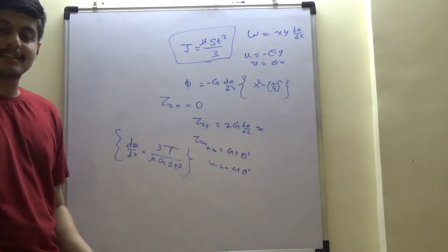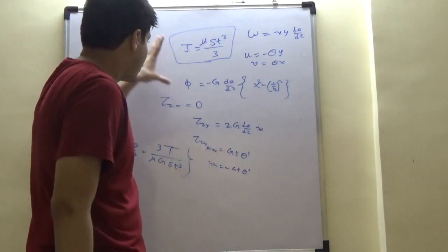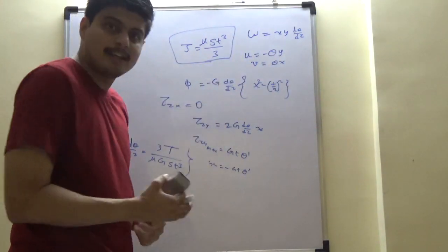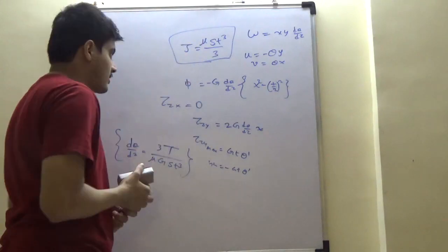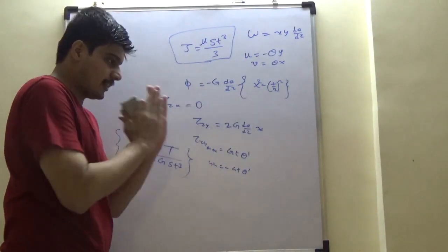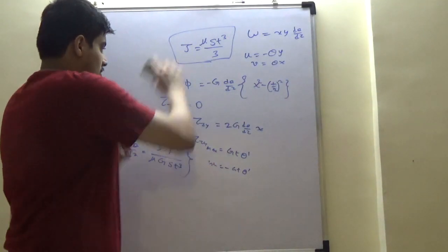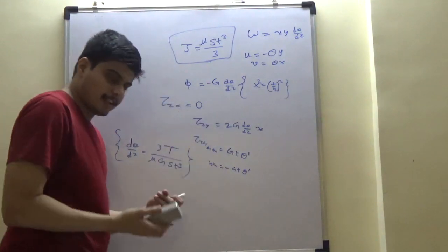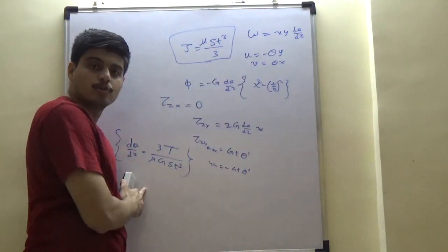And this was the third section on why thin sheets are important. For thin sheets, therefore, for s by t, Prandtl gave us this beautiful analogy and outcomes, and he gave the correction factors. So the entire problem is very easily solvable, and thin sheets are particularly important in our aerospace analysis, because of which Saint-Venant's warping function and the membrane analogy come together to give me this solution.